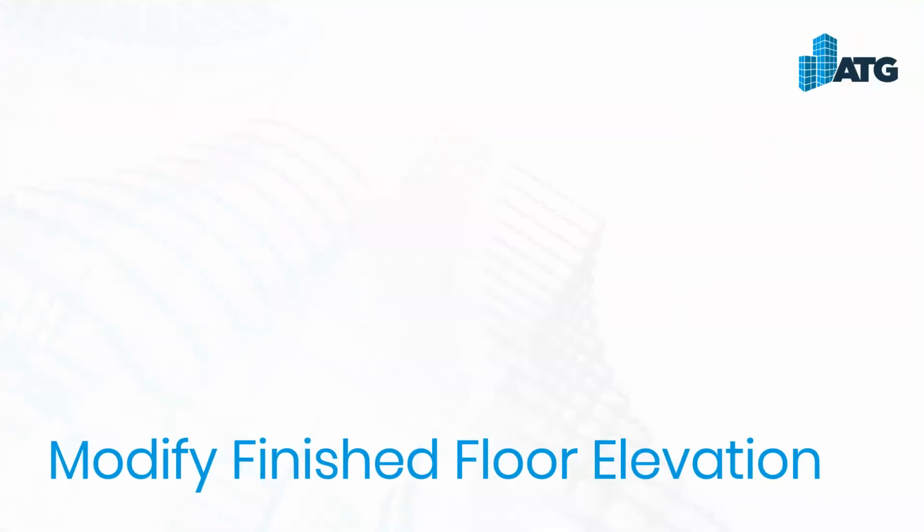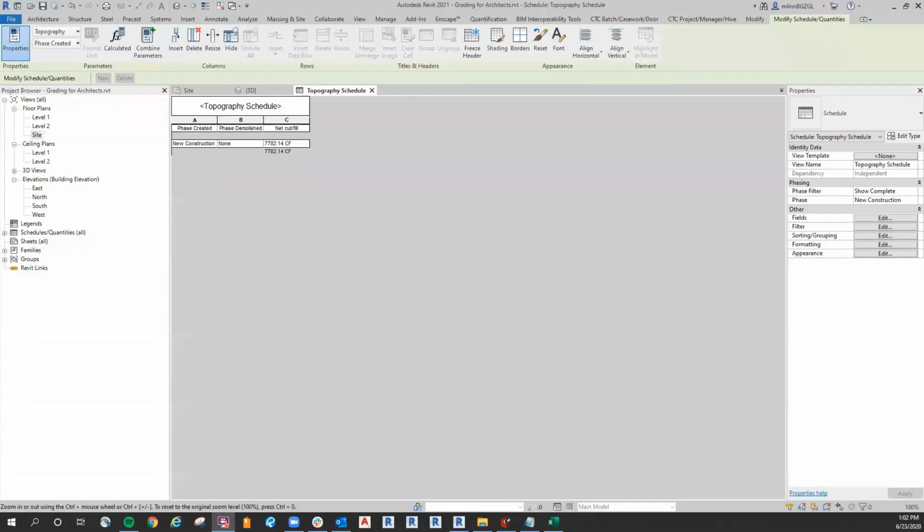Okay, so now we know how to create a schedule to measure the amount of cut and fill on site. Obviously, if you have a positive number, then your current design would require dirt to be hauled off the site, if you're trying to get back down to zero. And if your calculation indicates a negative number, then your design will require soil to be brought to the property. So let's use this information to revise the contours and or the finished floor elevation as required to come as close as we can to that net zero.